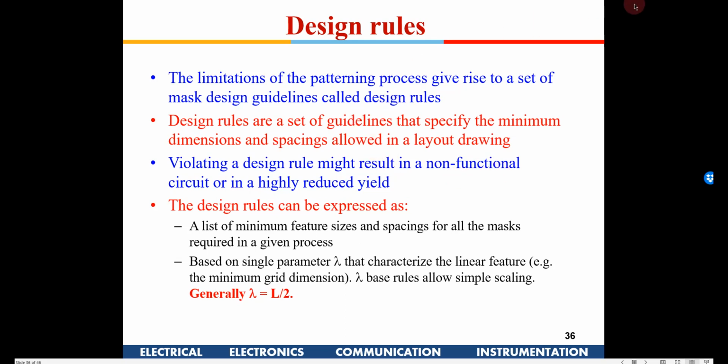Okay, thanks a lot. So every fab lab, depending on the technology they are using, they specify certain design rules which software like Cadence and others incorporate as DRC, design rule checks, when we make the layout. Essentially why you need to have these design rule checks is, when you are doing the patterning, there will be certain limitations, right? The minimum size of windows which you can cut, and also the spacing between two lines.